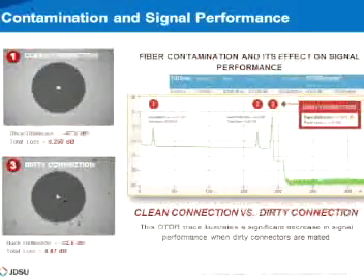Here you see the OTDR trace, and that shows what happens to the signal when the connector is dirty. The OTDR trace shows 3 different connectors in the link. The first 2 are clean, and the third one is dirty. I don't know if you can see, but there is a little particle of dirt in the core of the fiber that is creating 4.87 dB loss for that particular connector.